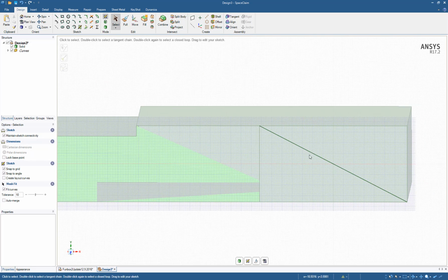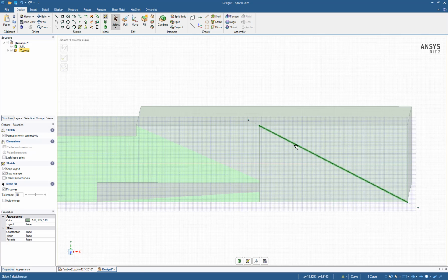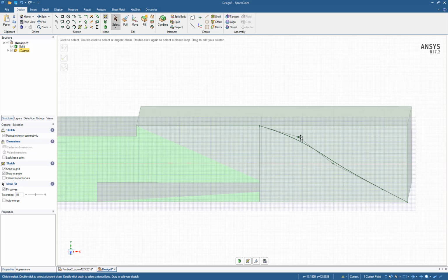And now it looks like a straight line, but since it's the spline, I can select this object, and you'll see a number of things come up. And the only thing we're going to look at right now are these different control points. So right now the line itself, the spline, is selected. I want to go up to one of these knots. We call these control points or knots. And notice that I can move this around, and that spline is going to change as a result of me moving this. We don't have an equation defining this. This was just free form. So we're not going to worry too much about how perfect it was to the original right now.